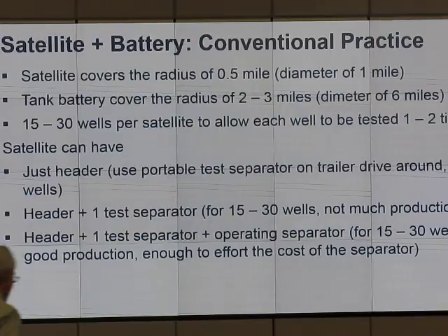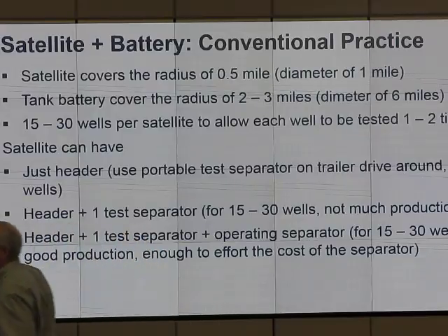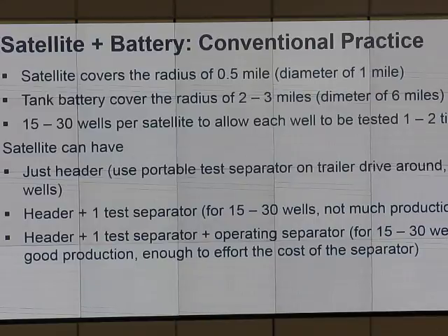In New Mexico or? Portable test separators are used if you're tying several smaller wells and you want to put them through a header, then portable test separators can be taken to the wellhead and test the well there. If you just have a few wells, you don't have that header distance to worry about, you're not using satellites, you take those individual wells to the battery, build a header there, and then go to a test vessel. So a portable test separator is kind of last resort.